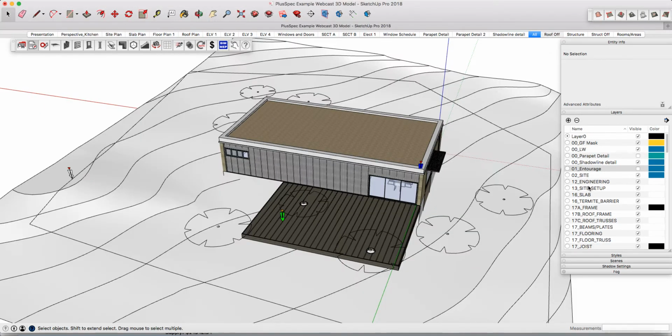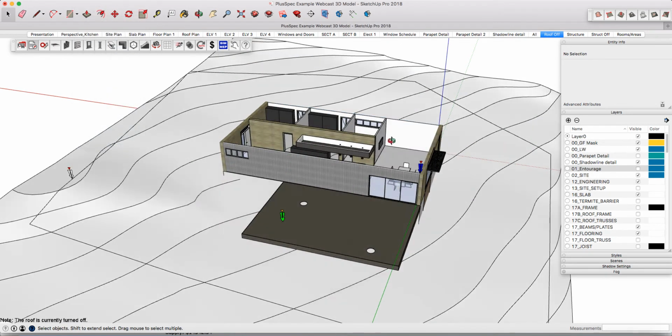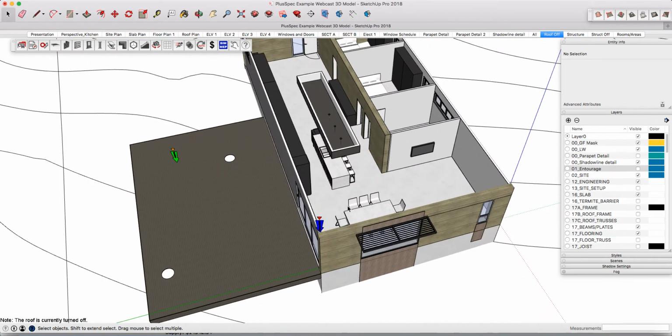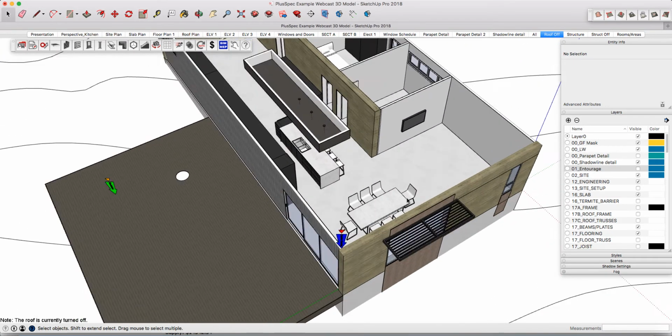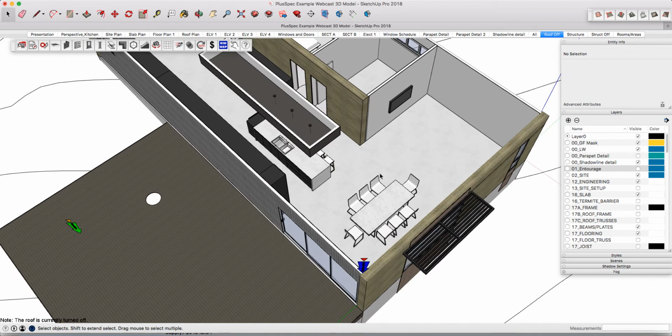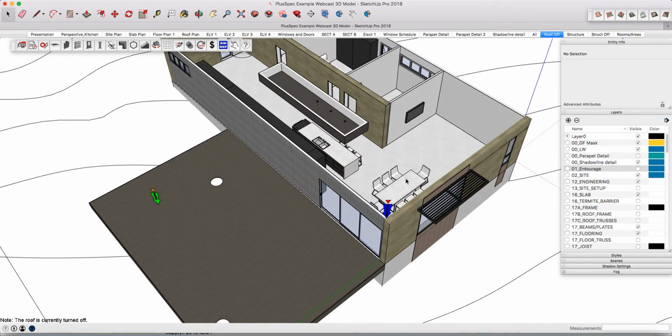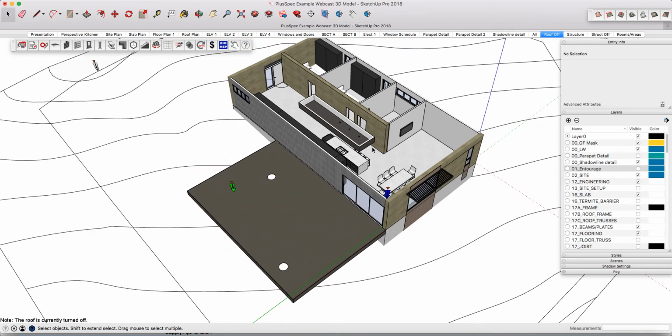Now, if I turn the roof off, I'll just quickly turn the entourage off and the shadows off. You could even start to use tags for objects. I wouldn't do this, and this will go on to our next part. But say for example, if you don't really want to touch an object, you could simply add tags. So, you know, you're on this table, you might want to add some notes. So again, you go into the tag tool, put a general comment or some kind of comment, and you could put the product URL or something like that. However, I highly recommend that when it comes to objects that you look at the BIM tool. So that's what we're going to focus on now.